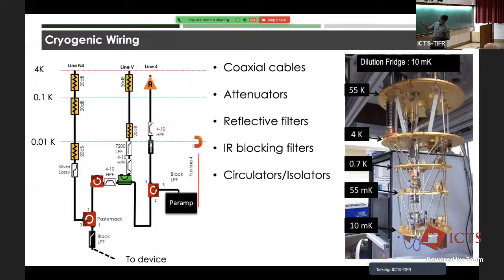So if there is some noise coming down this line, so this is actually the output line, you expect signals to go up this way. But these amplifiers here can actually radiate noise, and there could be other kinds of noise also. But this device here will actually prevent signals from propagating down in this direction. I'm just noticing that this arrow might be in the wrong direction.